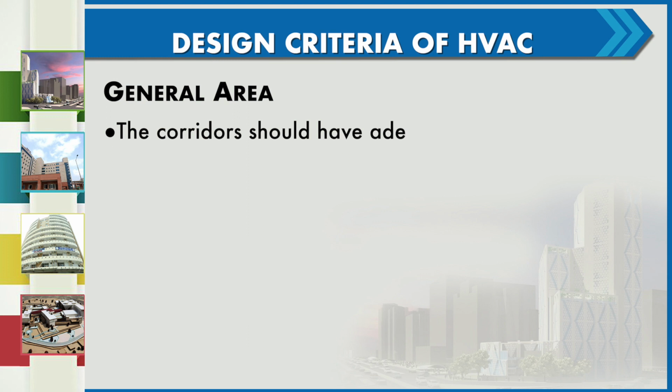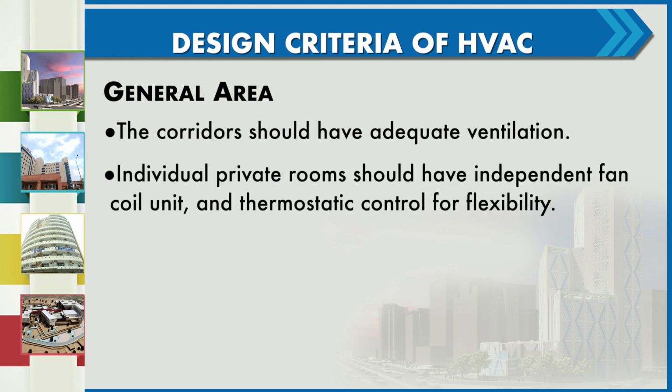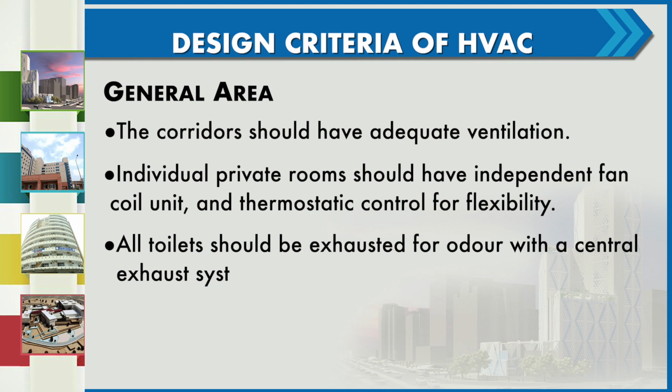The general areas. The corridors should have adequate ventilation. Individual private rooms should have independent fan coil units and thermostatic control for flexibility. All toilets should be exhausted for odor with a central exhaust system.